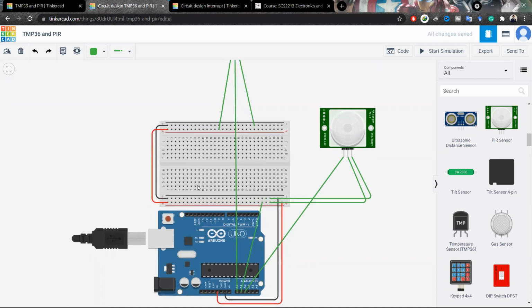In the breadboard, these two sections are connected like this, right? If you give some value to this end, you can take that value out of this point. This row is connected horizontally, and this row is connected horizontally too. But in the middle sections, this section is connected vertically.